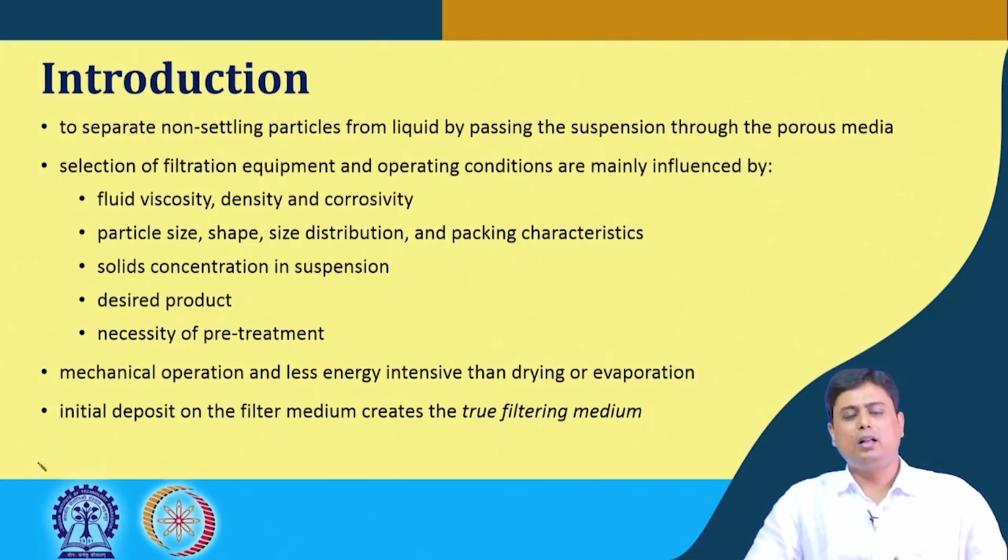So, the point is that if we have a clean surface of the filter medium, initial deposits sit on it and start to grow. The thickness of those particles then grows as bigger size particles and different types of particles stick to that cake. So, we call this thickness of solid particles the filter cake.